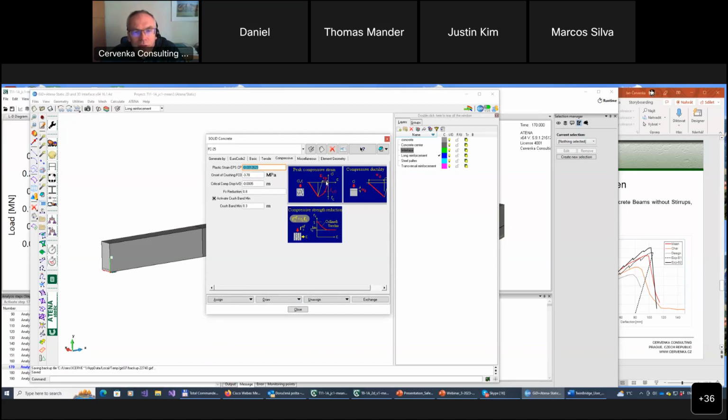Yes, it means the amount of plastic strains if you make a uniaxial test. This is the amount of plastic strains when you reach the peak. So if you have a test, then it's quite easy to extract: you just divide compressive strength by Young's modulus and subtract that from the total strain value at the peak, and you have this epsilon CP.